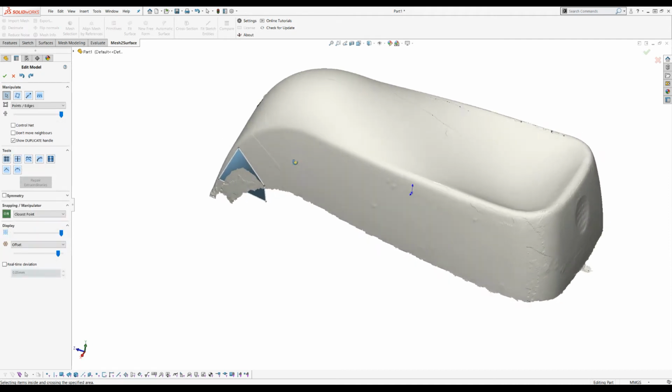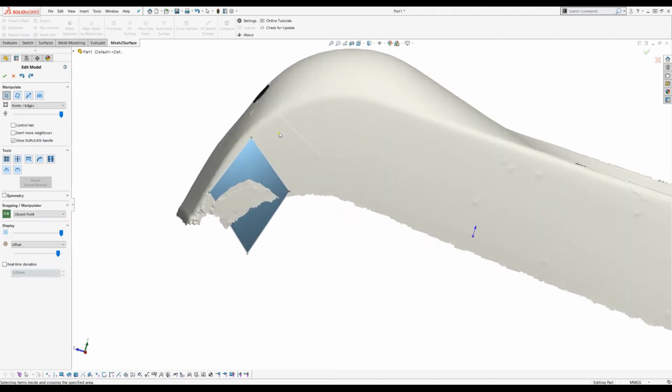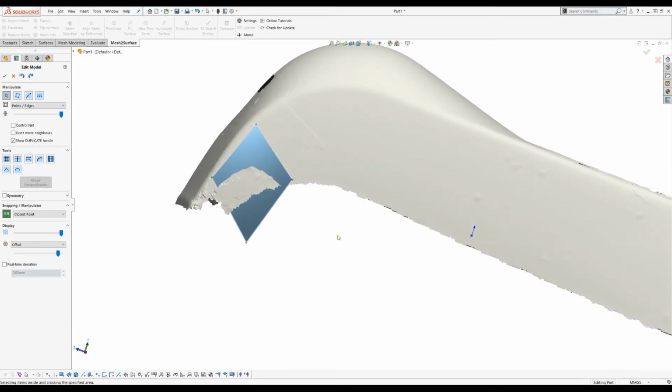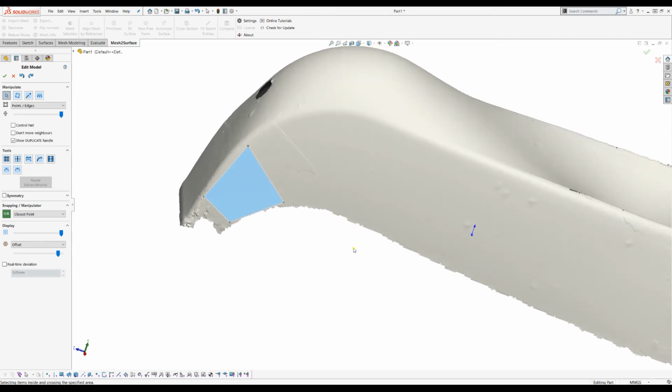So what happens now is that when you create your face and click, if you don't click on the mesh, it does a ray tracing. I mean, from the viewport, it tries to hit a mesh underneath, and if there isn't one, it just places this point somewhere in space, which in our case is not good enough. So what I need to do is just take this point, drag it, and drop it on top of the mesh. So now we are ready to go, and we can just use our standard approach with the duplicate mesh.